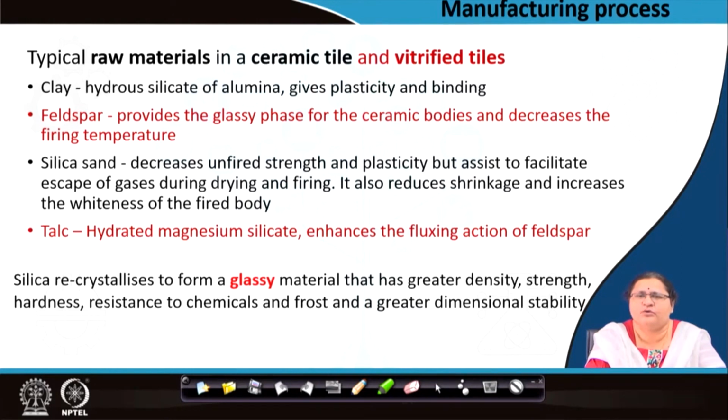How are they manufactured? How are they different from the making of a brick? Here you can understand that the raw materials have to be very fine and they have to be consolidated or compacted to a great extent, so that the porousness which was prevalent in bricks, allowing some 15 to 20% absorption of water, is prevented. That would give it more density, more strength, more hardness, and obviously the coating would give it further benefits.